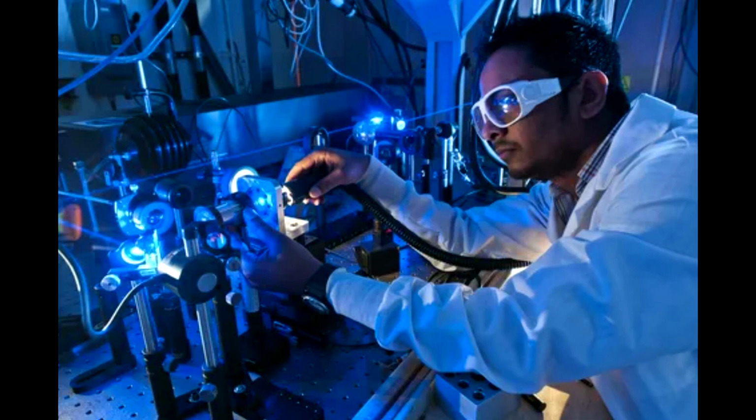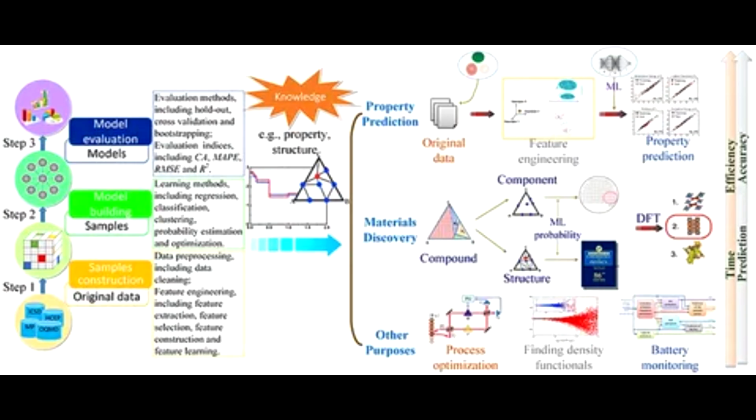3-4. There are two general classes of data logger. One is the static data logger and the other one is the dynamic data logger. The choice of use depends on the type and quality of data required. If the required data is very sensitive to time, such as impact, vibration and other high-speed phenomena, the dynamic data logger is required. The static data logger is sufficient for tests such as load, pressure and temperature tests.